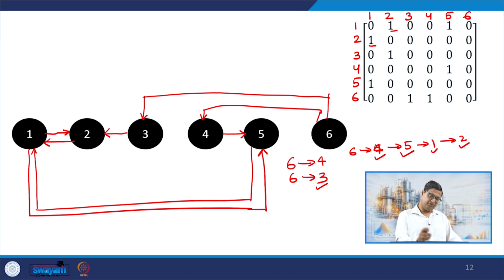So formally I can compute the reachability matrix for this, and what we should see is 6 is therefore the tank where I should give my input. I can go ahead and try for the other vertices to see if that is true, but I think it should not be true. From 6 only I can go everywhere else.